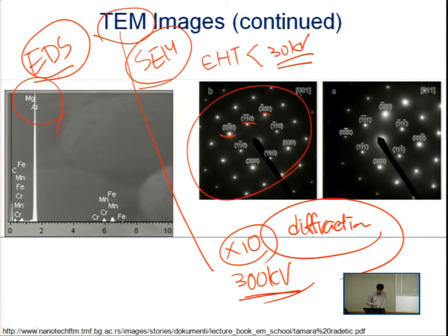Using the EDS attached to the TEM, we can also do compositional analysis. If we use WDS, which monitors the wavelengths of the X-ray, we can have much more accurate analysis of the compositions.